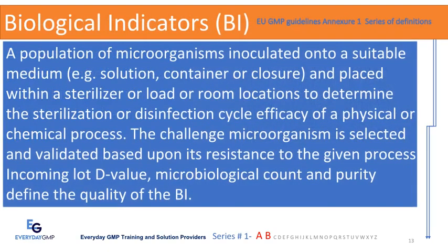Biological indicators: a population of microorganisms inoculated onto a suitable medium, e.g., solution, container or closure, and placed within a sterilizer or load or room locations to determine the sterilization or disinfection cycle efficacy of a physical or chemical process. The challenge microorganism is selected and validated based upon its resistance to the given process. Incoming lot D value, microbiological count and purity define the quality of the biological indicator.